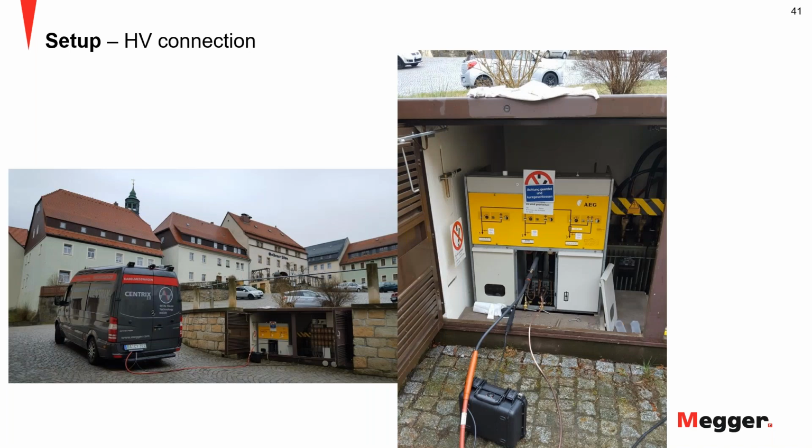It is installed in a way that you don't have any significant corona. You have a little bit more background noise with this test setup, so you're losing measurement accuracy. But the customer said, I don't care. My policy says I do not take any action until X, Y, Z values. So I can have more comfort and more safety because I don't have to make a special test environment here